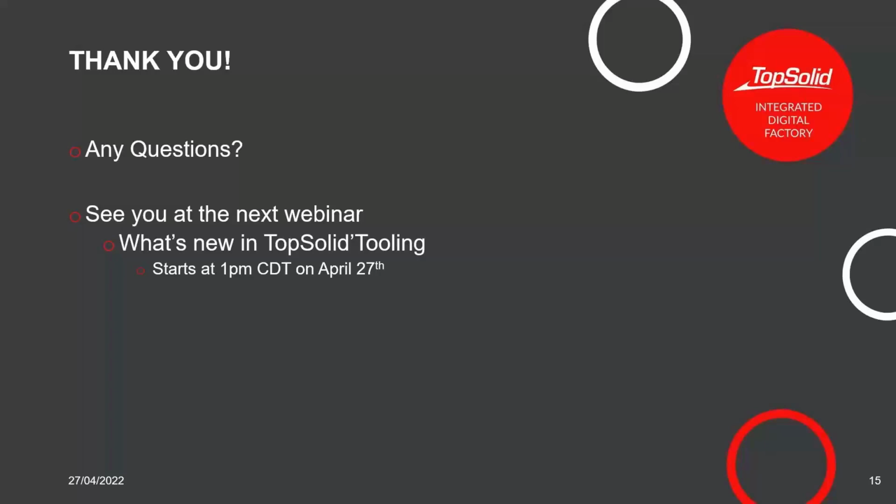Personally, my piece of advice to you guys is anything you turn on during the translation makes the translation take longer. Okay? In some cases, it's worth the effort, and you'll just have to experiment to find out when that case is. Personally, I like to import it without any of that stuff turned on and see how it comes in, play with the standard tools, and if I need more, I may turn it on again and try it.